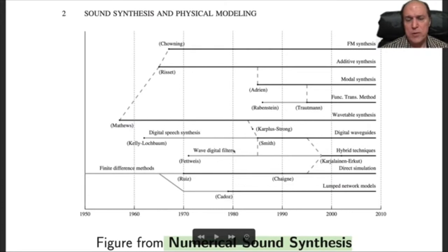In any case, wave digital filters are from Alfred Fettweis, and it's a scattering formulation of analog circuits such as RLC: resistor, capacitor, inductor. Those are normally done as lumped systems with just voltage and current, but you can also express the voltage and current as traveling voltage waves and current waves, and then you get the wave digital filter paradigm. And it has excellent numerical advantages, it's been used extensively for circuit modeling, and it's still one of the very best ways to go for modeling a circuit.